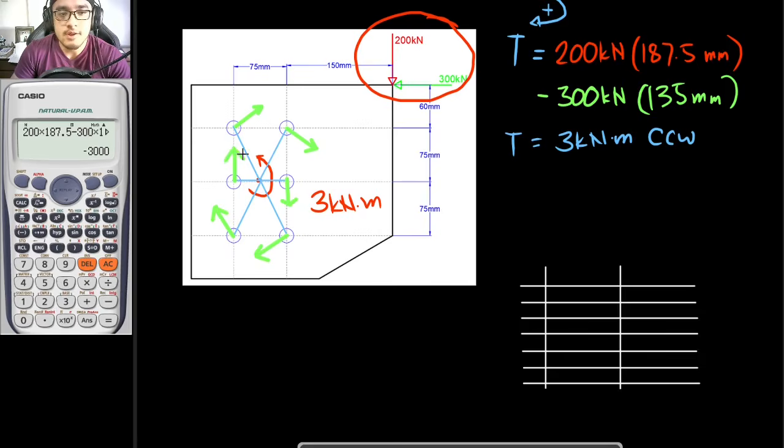Are there any questions? If none, I will repeat that these forces are perpendicular to the line that I have drawn earlier, which is a line directed from the center of each of your bolts to the centroid of your bolt group. And it is in this direction, not the other way around, because their use is to cancel this torsional moment.